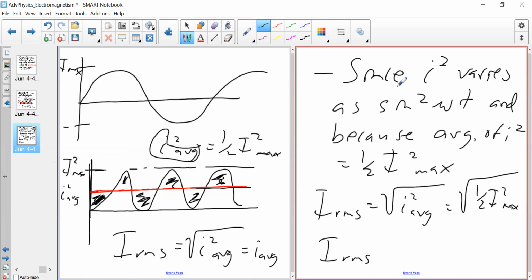This is going to bring it home. If this was here, it was all kinds of sloshy and confusing. Well, let's take a look at it from the math perspective and understand it. The IRMS, this value, is going to be √2/2 of Imax, or basically 70% of this, which we're not concerned with because direction doesn't matter. So when we have a power outlet, 120 volts AC, that's RMS. That's what we were concerned with. We design our AC voltmeters and stuff like that with RMS in mind.